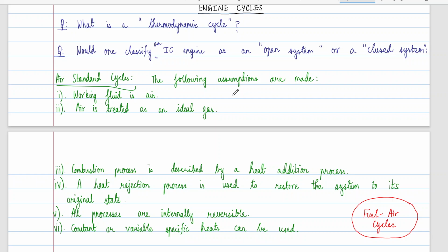Yes. So what I'm asking is, will the electric motor with 10 kilowatt power be able to generate this much torque at 7,000 rpm? If we use the formula, when I give this 7,000 rpm and 110 newton meter of torque, I'm obtaining about 70 kilowatt of power.